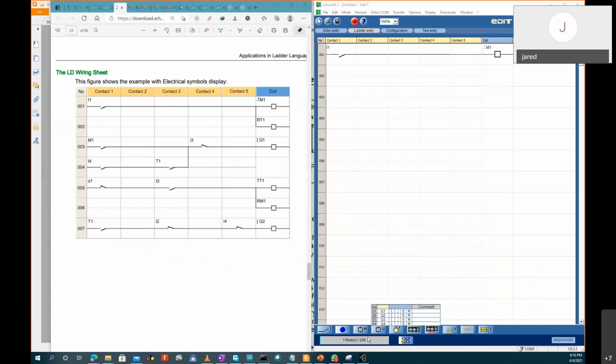So you see, this is telling you the number of blocks, the number of ranks. You cannot exceed more than 240 ranks. If you exceed 240 ranks, your PLC is full, so your memory is full. At least try to maintain 80% of your PLC program, the same way as your PC. You don't use 100% of the hard disk. You leave some space for the PLC to breathe.